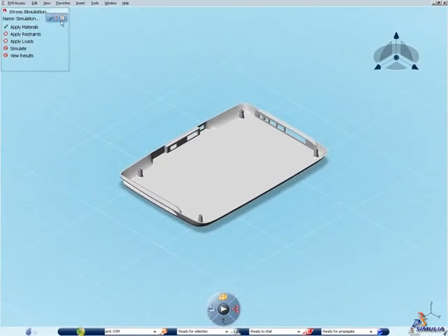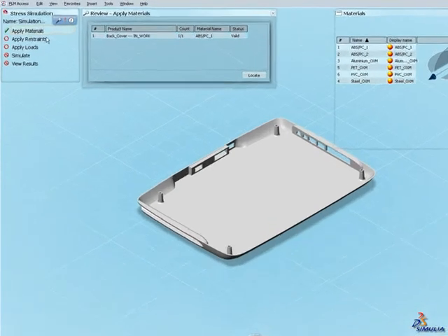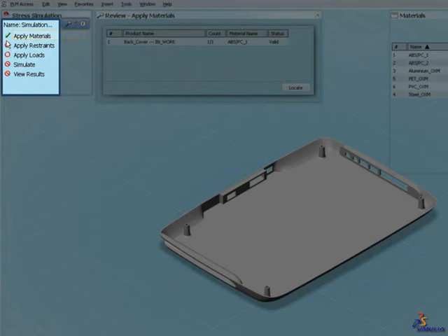So let's follow the simulation panel and start with the material definition. In our case, DesignSight will automatically get the material assigned previously in the part design workbench. I can still review which material has been assigned to be sure it's the one I want to use. One other point we can see is that as the step is completed, a green check mark appears next to it. This will be the case for each step, making it easy to determine where we stand in the model setup.